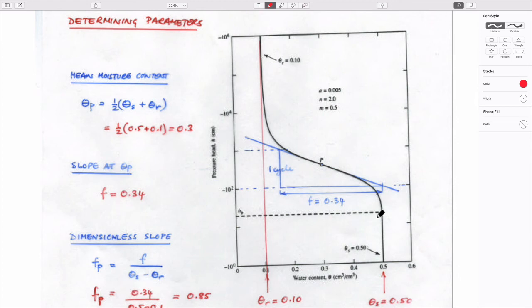You take the curve that you have, which is a real data curve. It must have a porosity in this particular case of 50%, right? Because this is the fully saturated, 100% saturated part. It must have an irreducible water content of 0.1. And these are the magnitudes of the pressure head. So this is the same as matrix potential, so this is P_C over gamma_W, this term here. And the recipe to get the terms m, n, and alpha is to do this.